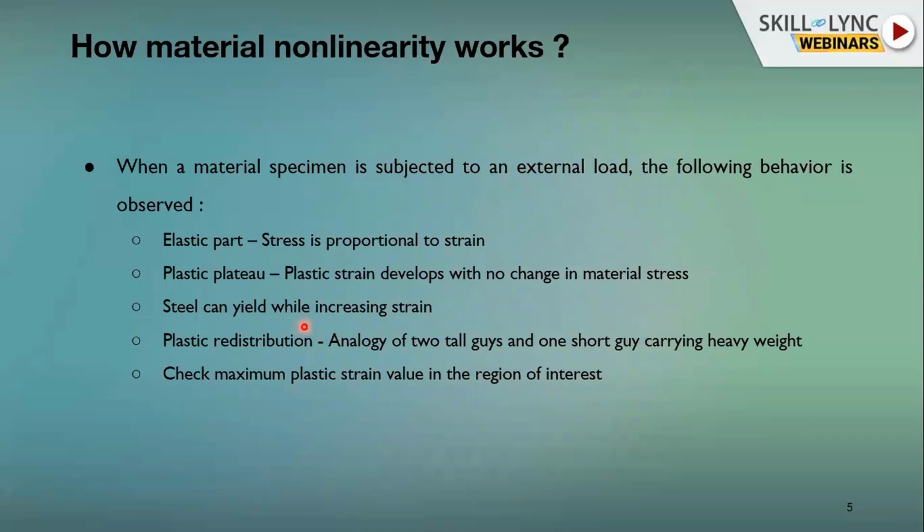But definitely there will be a deviation between analytical and simulation. However, if you find the stresses to be unrealistic, you have to check a few things beyond an elastic limit. How high that value is is worth looking at in linear statics, because linear statics is not going to give you the realistic picture beyond the elastic limit.